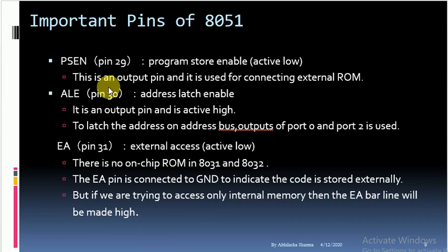This is an output pin, and basically it is used for connecting external ROM. When some version of the 8051 microcontroller does not have on-chip ROM and we want to connect some external ROM, with the help of this pin we can connect the external ROM with the microcontroller.